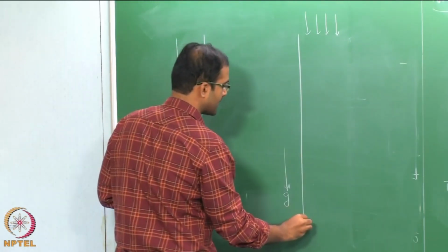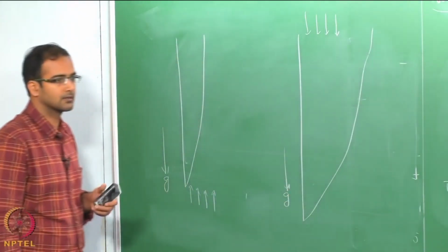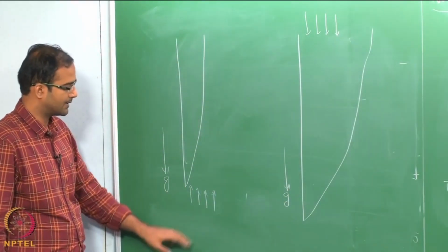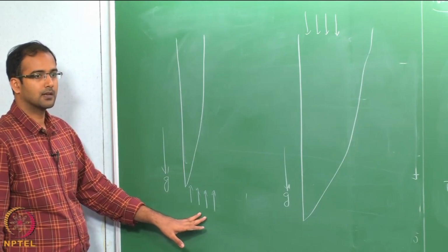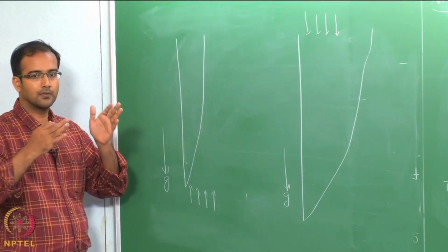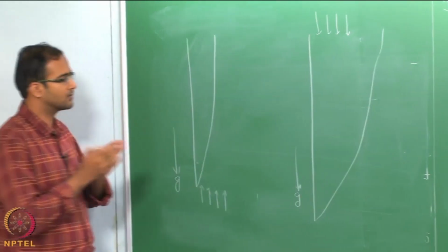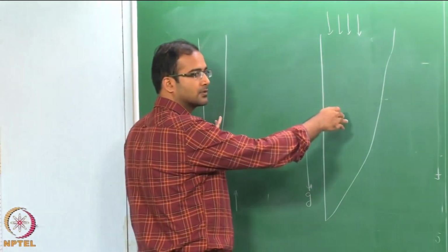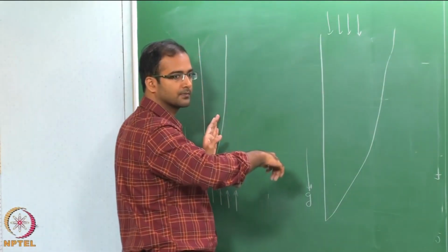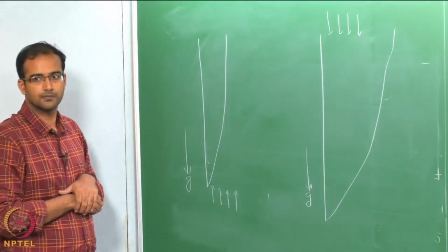Okay. So in this case you will have a boundary layer growth. You should understand that since there is a forced convection motion in the upward direction, this will tend to compress the boundary layer compared to the case where you push the bulk motion downwards. So in this case the boundary layer will look more stretched out.